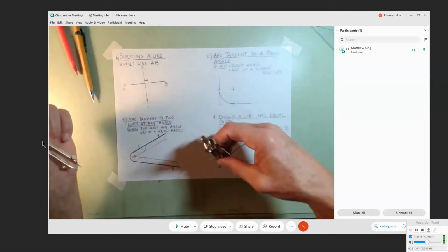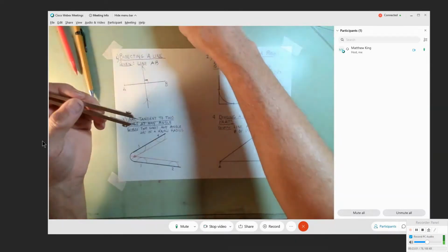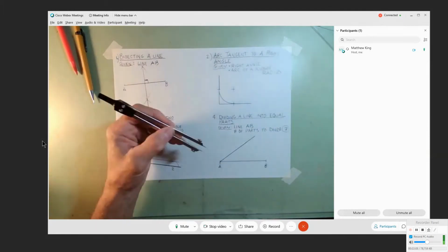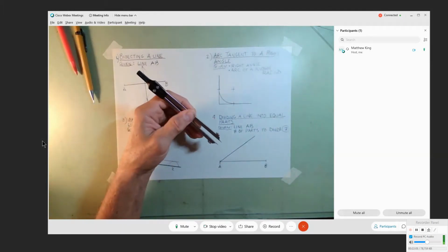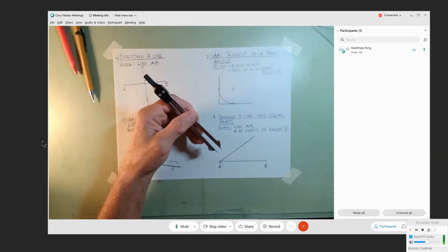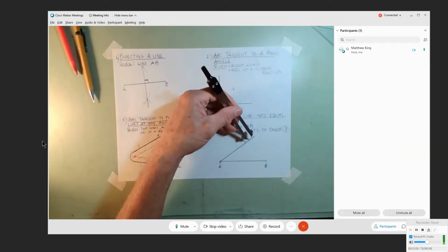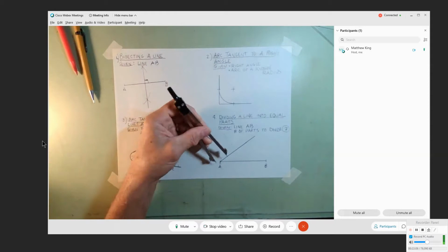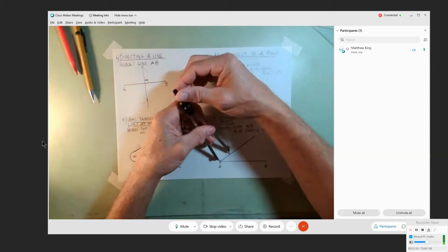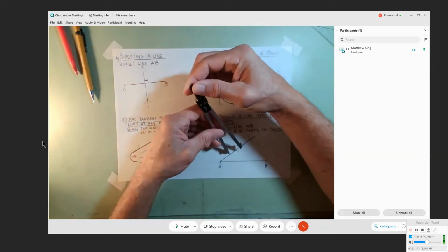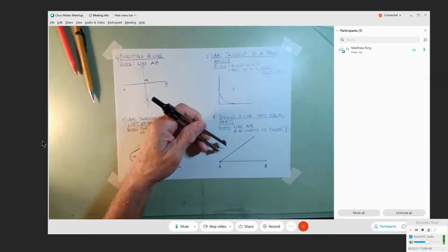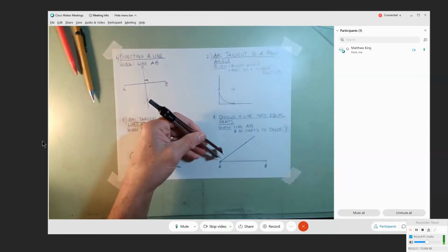All right, so instead of striking arcs with our compass and leaving a trail of lines here, what we're going to do is stab little holes in the paper. Now, I need to adjust my dividers to no specific amount other than I need to lay out 7 of these, one after another on this line. So if I opened it up to this and I would step off this amount, I'm going to quickly run out of line before I get to 7. So I'm going to bring that down smaller.